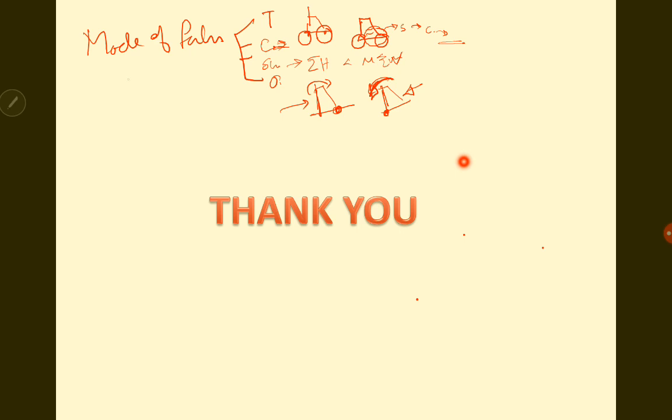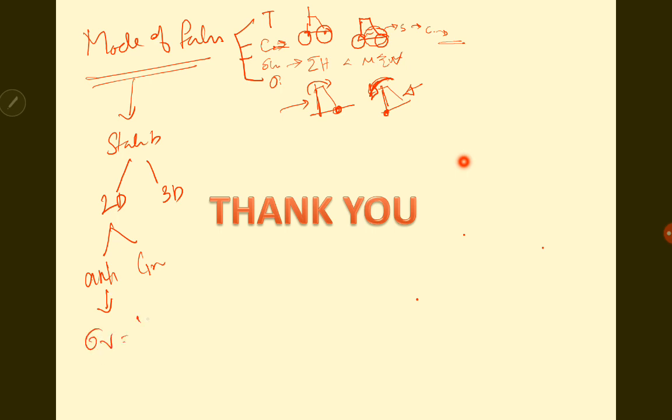Now, having understood these modes of failure, you can check the stability of the dam. You have 2-dimensional and 3-dimensional methods. In the 2-dimensional method, you have analytical and graphical methods. In the analytical method, you just check using the equation sigma V is equal to sigma V by B into 1 plus or minus 6e by B. You'll be finding sigma V, sigma H, sigma M, and then you'll be finding the eccentricity and checking if it is well within the limit, that is B by 6 limit, using the middle third rule.